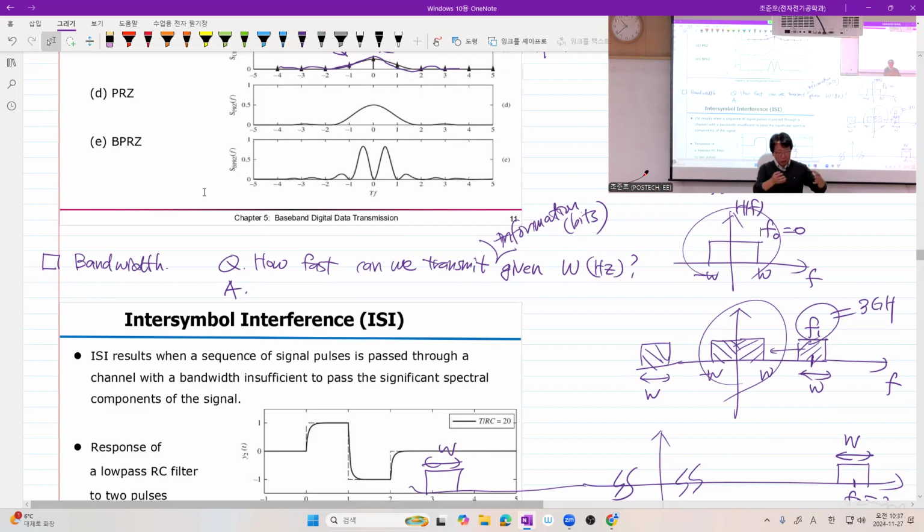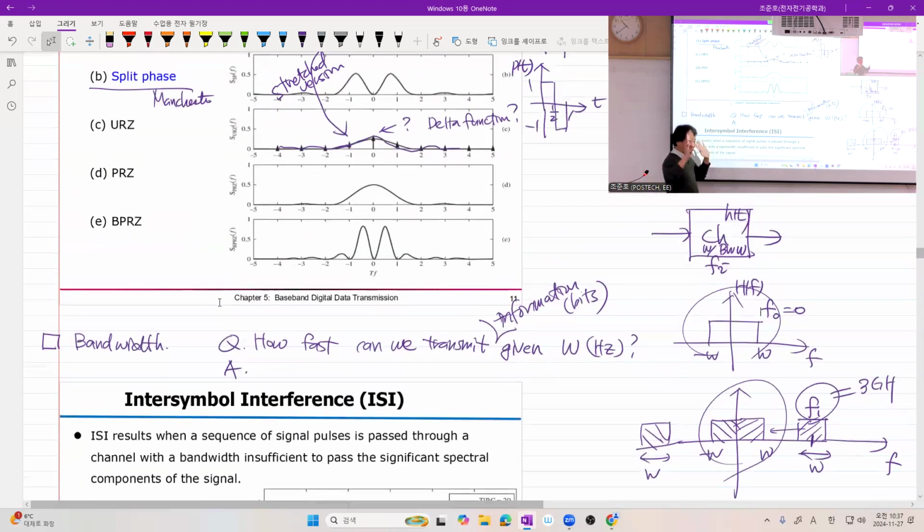But if you want to build almost the same functioning radio at 30 gigahertz, suddenly the same equipment, functionally speaking, may be priced 100 or 200 times higher. I believe that was one of the reasons why our 5G frequency range 2 equipment is not sold well. It is too expensive. There is too much RF loss, leakage, and a lot of troubles. But anyway, I'm not going to talk about that reality.